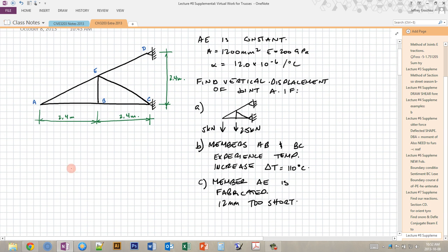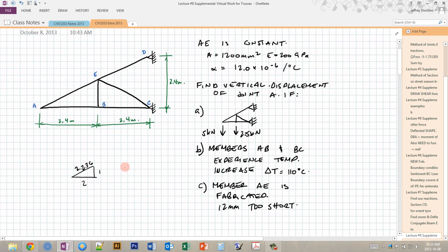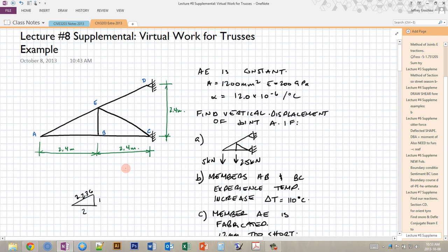So first I'm going to use the slopes in order to calculate my truss forces. It's nice to know that we have a ratio of sides here, and all of these triangles happen to be the same. So if the vertical is 1, then the bottom is 2. So this length is 2 times the height, and then the diagonal would be 2.236. Now I'm not going to go over the truss analyses for all of these trusses, so you might want to check out my other video where I describe the method of joints, which is the way that I solve these trusses.